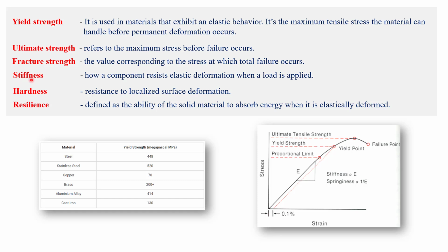Yeah. The next important terminology is the stiffness. So what exactly it does is, let's say, how a component resists the elastic deformation when a load is applied. So if you want to check the stiffness of the component, whatever the load you're going to put, that should not make the component deform. Whatever the load you're going to apply, if it is in that limit, we call it as stiffness. So how stiff the component is. Stiffness is directly proportional to Young's modulus. Okay, so you just need to remember that.